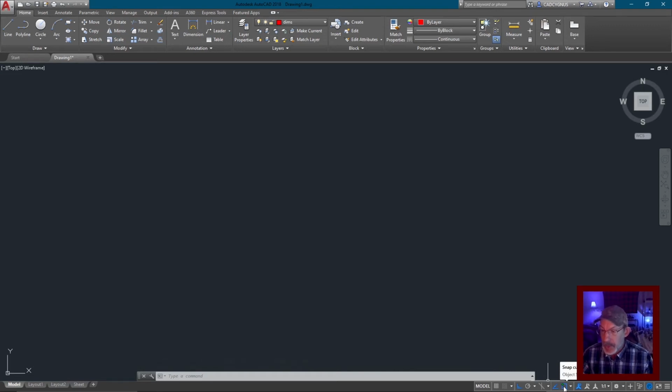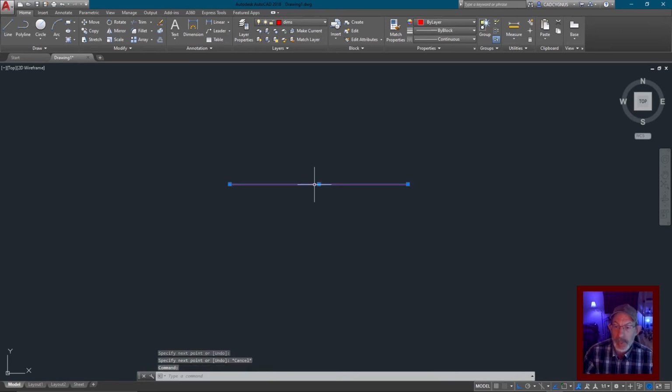Now, the other main thing in this course that I'm trying to show you is your snapping references. I've had people come in there and have that turned off and say, why isn't anything snapping? Why don't I find my midpoints? Well, what's happening? And they'll turn that off. Let me show you what happens to a line when you do that. And then you hold the line over it. You have your end point and your midpoint and your starting point.